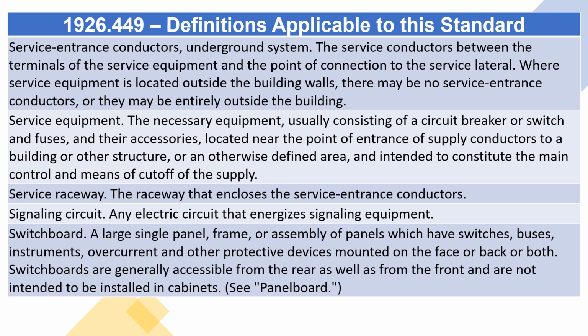Service entrance conductors, underground system. The service conductors between the terminals of the service equipment and the point of connection to the service lateral. Where service equipment is located outside the building walls, there may be no service entrance conductors, or they may be entirely outside the building. Service equipment. The necessary equipment, usually consisting of a circuit breaker or switch and fuses, and their accessories, located near the point of entrance of supply conductors to a building or other structure, or an otherwise defined area, and intended to constitute the main control and means of cutoff of the supply.